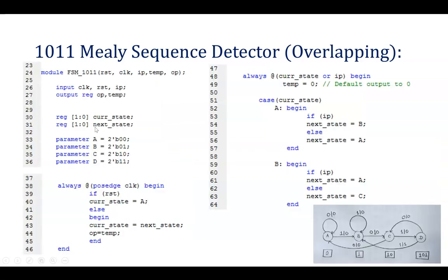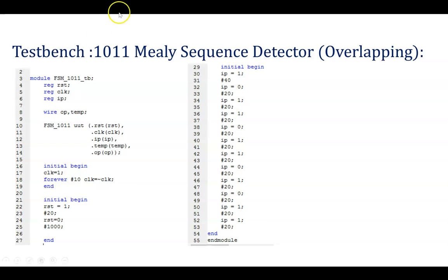So these three inputs we need to provide using the test bench, because at this moment hardware is not created, that's why you can't give 1 and 0, that is VCC and ground. So you are testing your design, and that's why you need to give soft inputs. That soft input you need to generate, and that generation is possible using the test bench. So for that only you are generating a test bench for providing soft input or stimulus for your design.